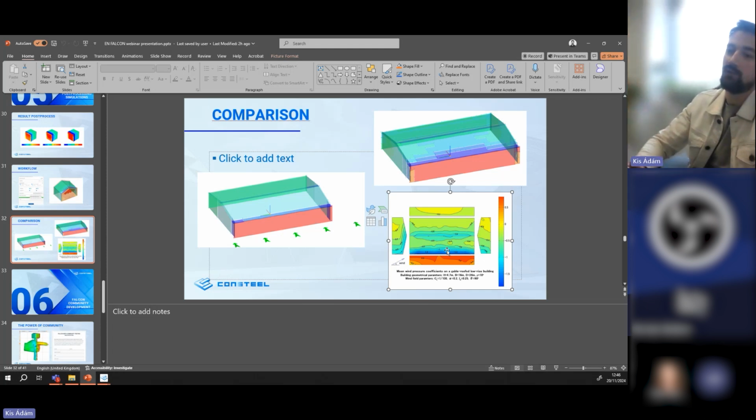So at the end of the day, it is not always the case that we get these F zones, but for example, from the wind tunnel testing, we have these minus 1.4 at the very edges, we have this minus 1 value at the so-called G zone, and we have this distribution like this C-shaped,